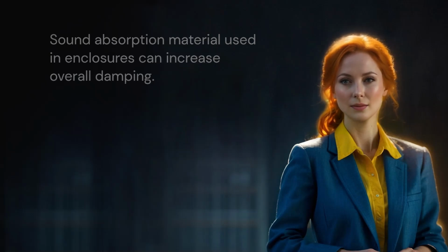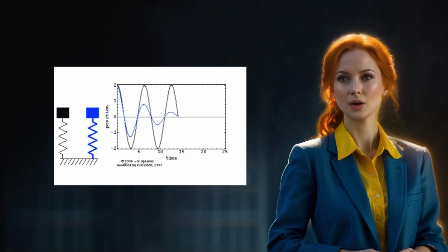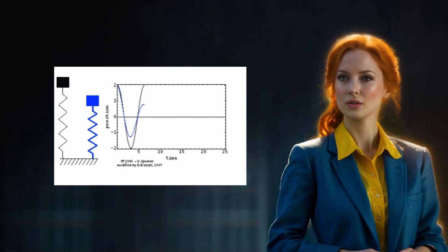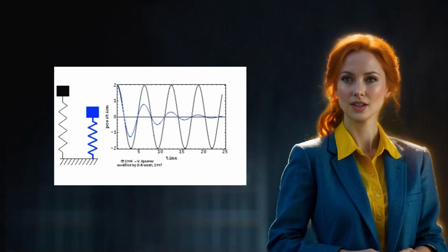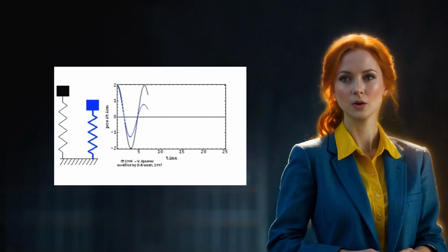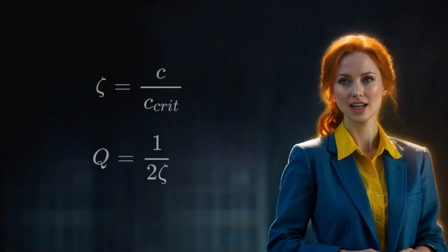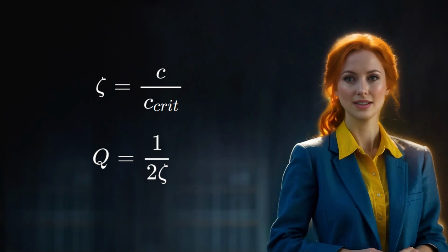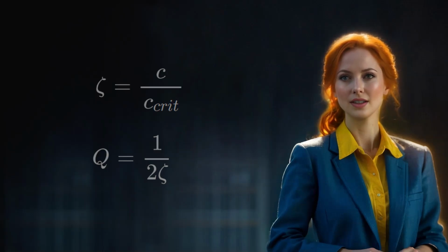The illustration to your left demonstrates how a mass suspended on a spring can behave differently as a result of change in the damping ratio zeta, or the fraction of critical damping, to put it more precisely. In the speaker society, the quality factor, Q, is preferred over the fraction of damping ratio, zeta. Although they come from different origins, these two factors can address the same issues and can easily be converted to each other by a simple relation, Q equals 1 divided by 2 zeta.